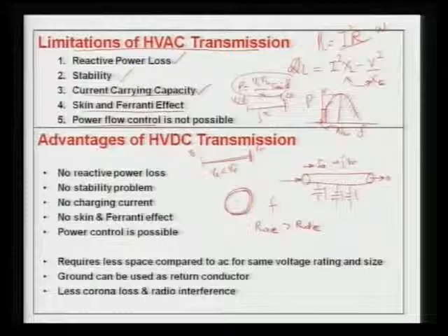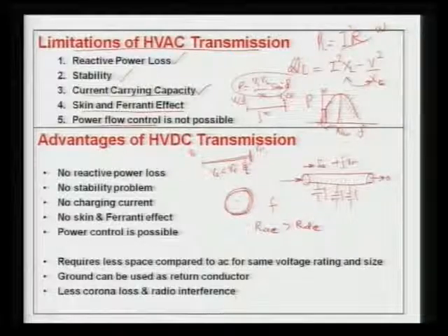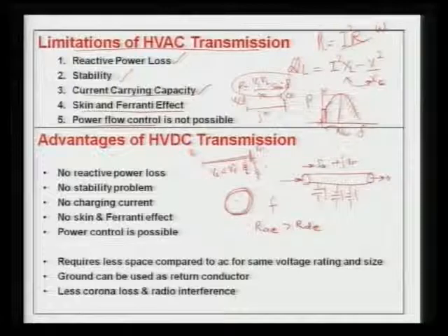So we go for various mechanisms to limit this voltage, especially if you are charging the line with no load, because then high voltage will be there at this end, and again there will be tripping of the system. So we put reactors: line reactors if the line is very long, and if you still require more reactive power, then you can put a bus reactor, and sometimes we also use tertiary reactors.